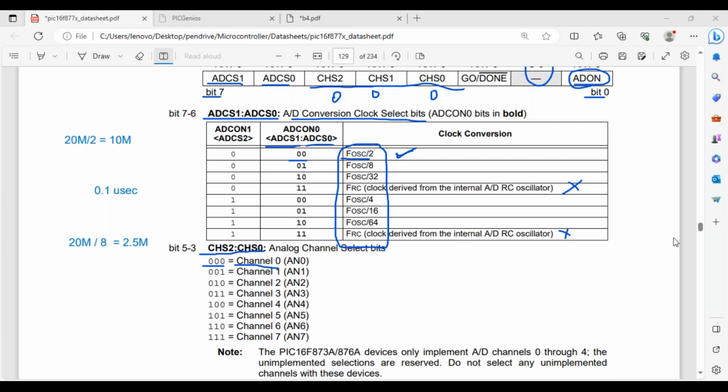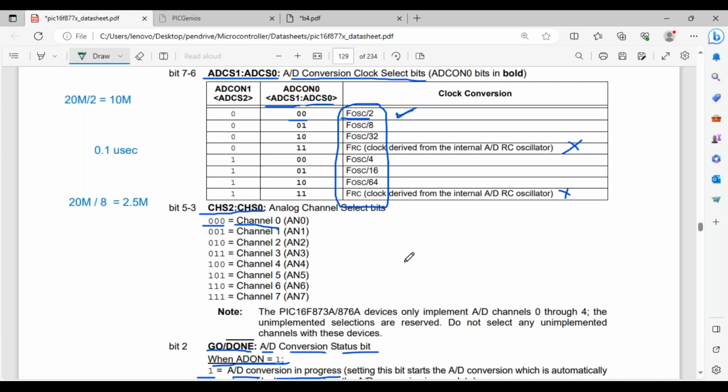And how to generate PWM using timer? Can you give one example? I'll come to that, I think. Okay, let me give a small idea. I'm not supposed to give hints about the assignments, but anyway, I'm giving you a hint. If there is a frequency of 5 hertz, first you have to calculate the period of each pulse. Then whatever on time and off time is there, you have to achieve that with the help of the timer.